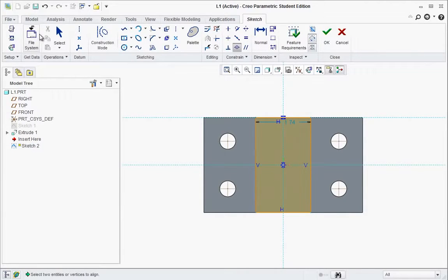So let's go ahead and go to the normal tool, which is for dimensioning. Select the top line, middle click on your mouse button. That middle, look at the middle mouse. Make sure it's that scroll. You push it down like it's a mouse button. This is going to be 1.5.